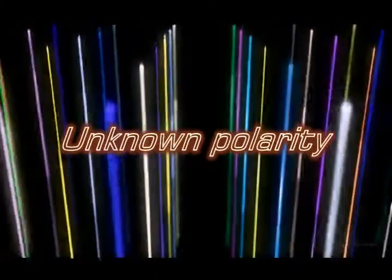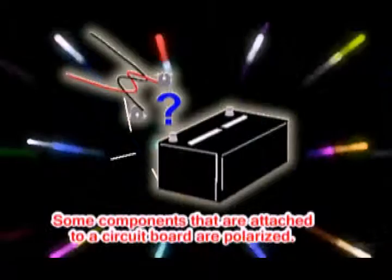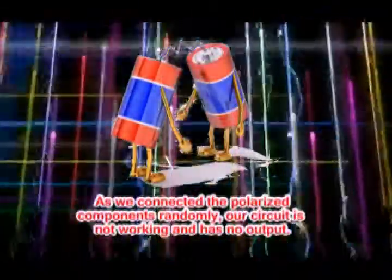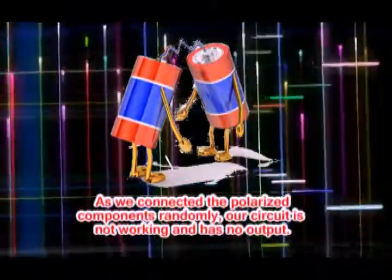Last but not least, the polarity of some of the components was unknown. Some components that are attached to a circuit board are polarized. This means that one side is positive and the other side is negative. Thus, we have to attach them in a certain and right way. As we connected the polarized components randomly, our circuit was not working and had no output.